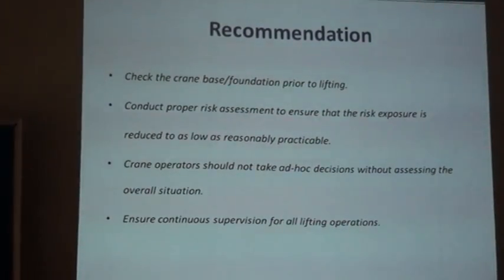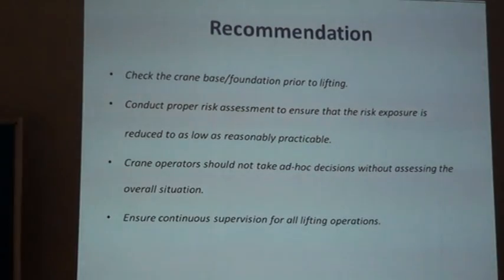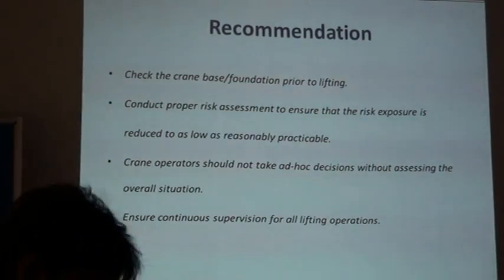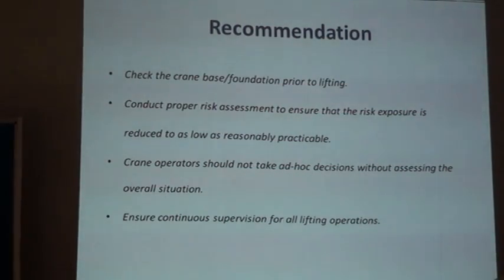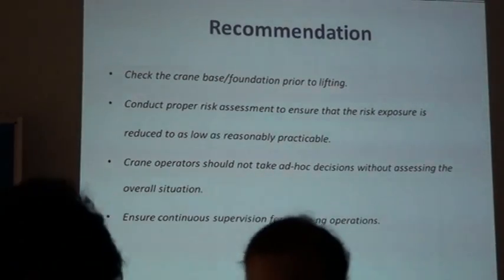The crane operator should always listen to the signaler. We cannot carry out anything apart from what the designated signaler instructs. Ensure continuous supervision for all lifting operations.